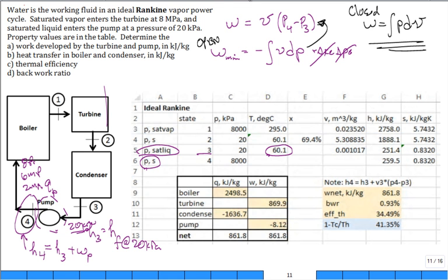And so if V isn't changing, it's constant, it comes outside the integral. Boom, there you go. What about this negative sign? Well, we're assuming that we know the direction of work into the pump, so we take care of it. But that negative sign corrects us for the traditional direction of the work transfer in a generic control volume. Okay?